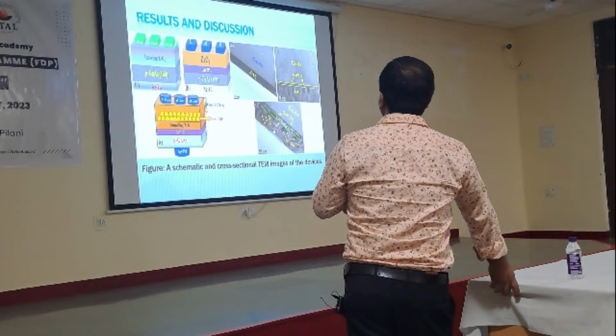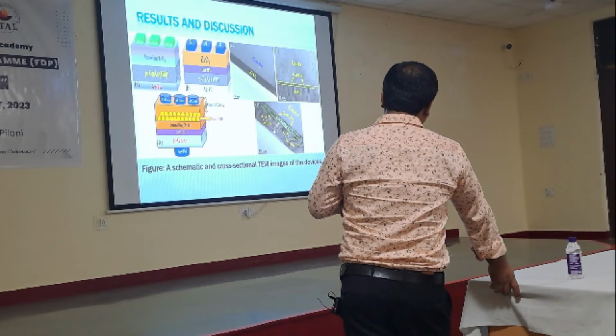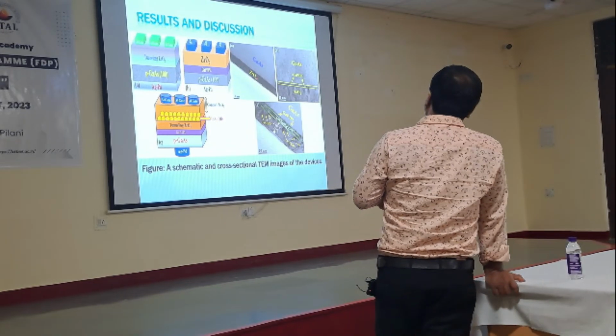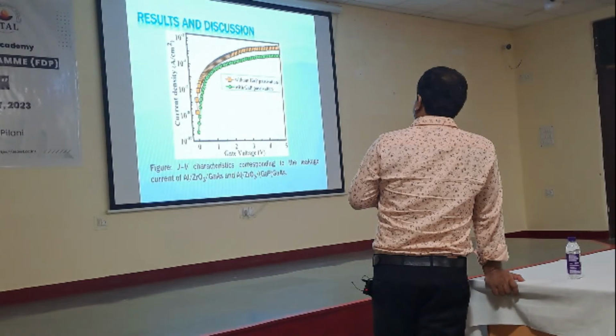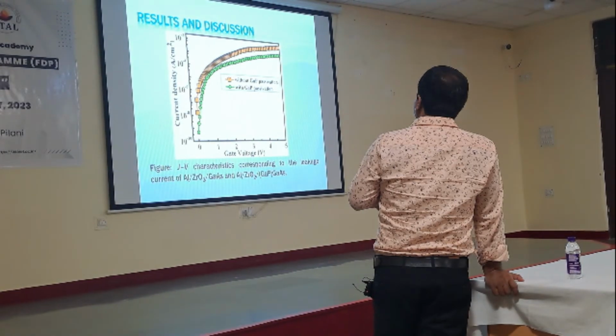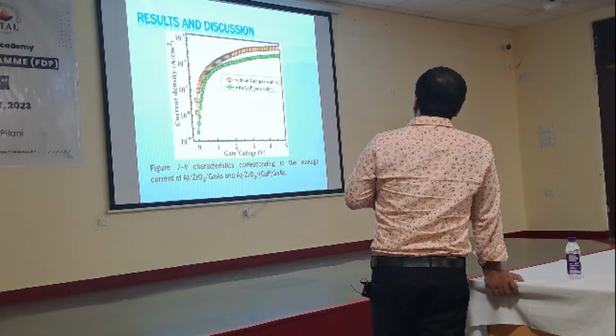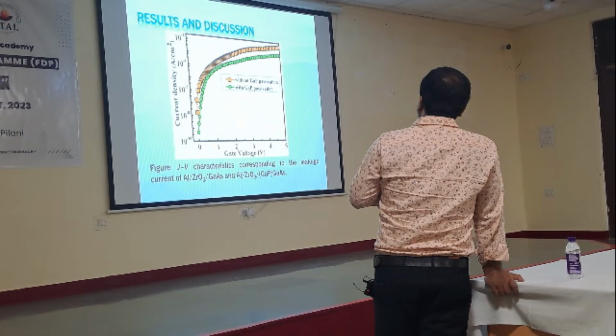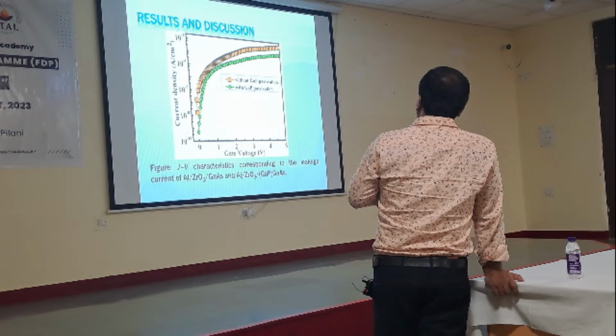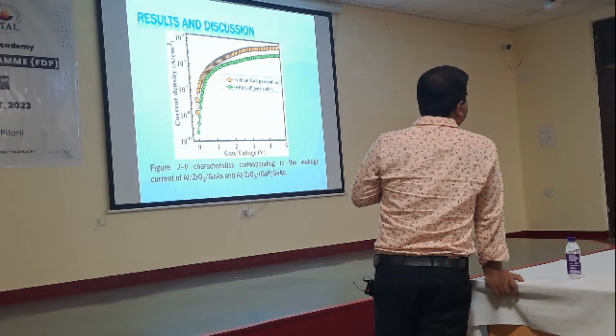For all the corresponding device structures, there is a cross-sectional TEM, or HR-TEM, where you can see all the individual layers stack by stack. Again, when you passivate the device surface with a gallium phosphide passivation layer, the leakage current will be low, and without the passivation layer your leakage current will be higher.